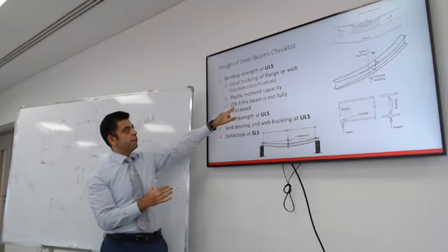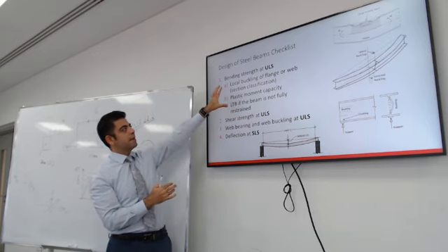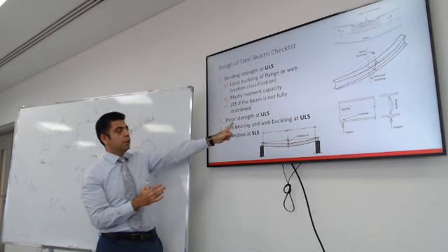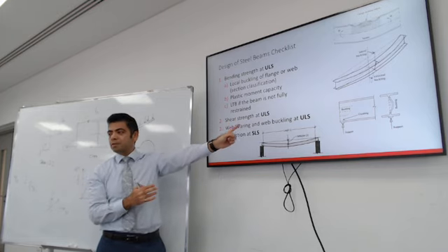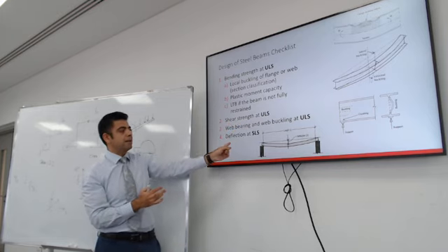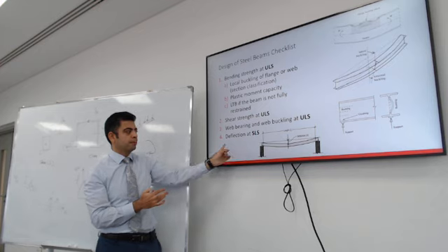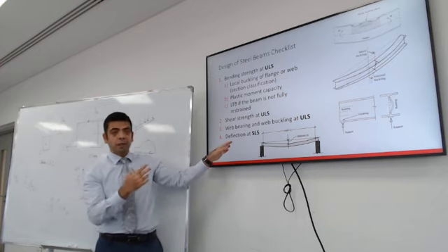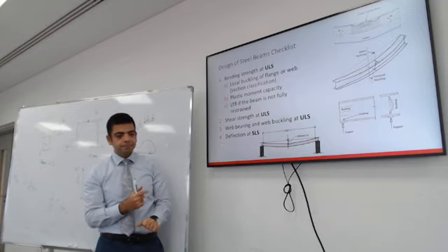Once you are finished with this third check, that's the bending check of the beam. You need to check for shear. There are different failure types for shear. We'll deal with this next week. And you need to check for deflection as well. Towards the very end of the presentation, I have the equations for shear.